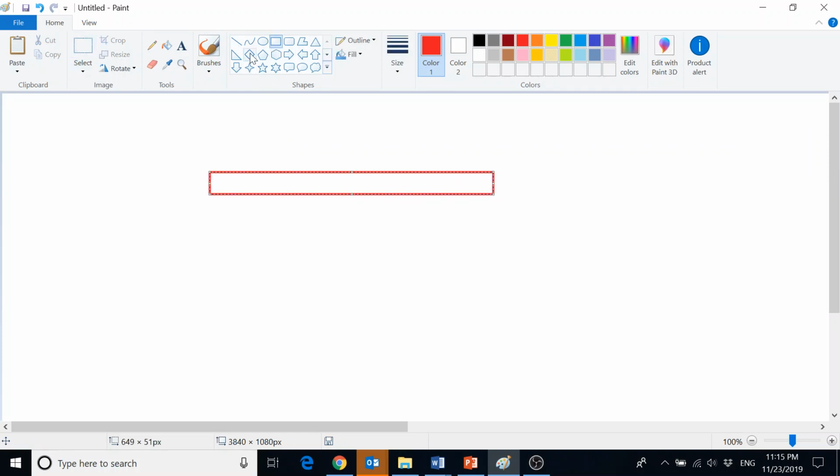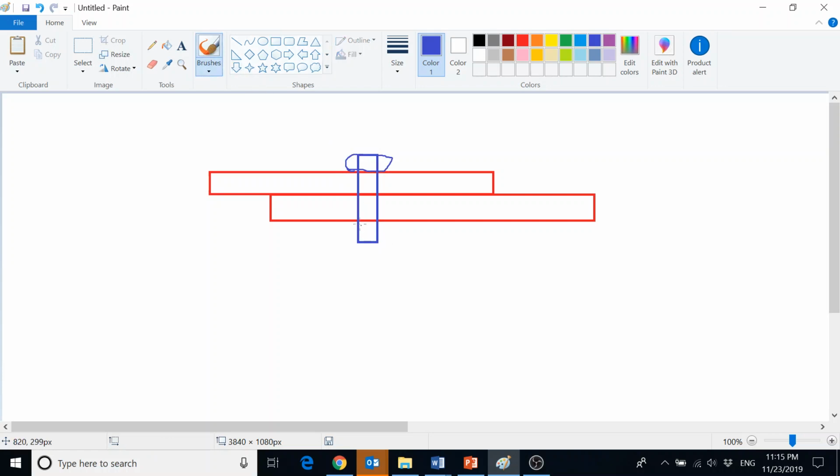So you have two steel plates you want to connect together. Let me change the color. You throw a bolt in, okay? Let's consider this is a high strength bolt, and then there's a nut. What it does is that you keep cranking this nut. In the end, there will be a huge tension force within your bolt. Now, this tension force, which we call pretension, creates a compression force between the plates. So if you look at this surface in between the two plates, they're actually under a huge amount of compression.